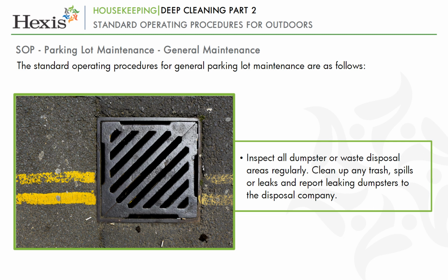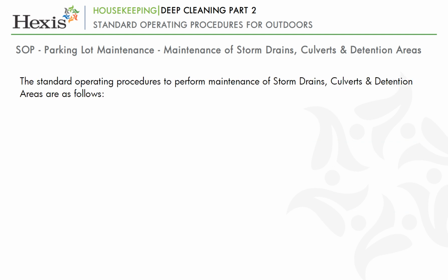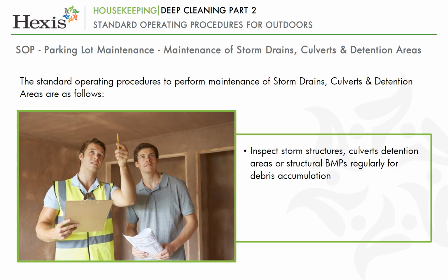Inspect all dumpster or waste disposal areas regularly. Clean up any trash, spills or leaks and report leaking dumpsters to the disposal company. The standard operating procedures to perform maintenance of storm drains, culverts and detention areas are as follows. Inspect storm structures, culverts, detention areas or structural BMPs regularly. Suggested frequency: weekly, for debris accumulation.